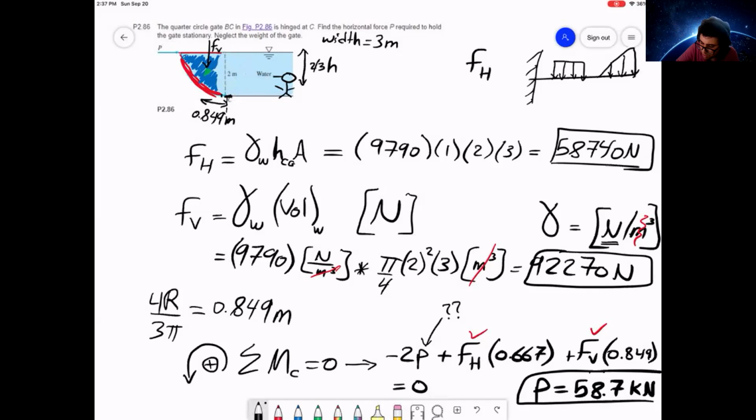If you look at this one, what's the pressure at this point, right at the top? That's what we found, right? The gauge pressure at the top. Not P, P is a force, but I'm asking what's the pressure at this point, right at the top, at ambient conditions. Oh, that's ATM. So if you're measuring gauge pressure, because that's what we like to deal with, it's basically 0.